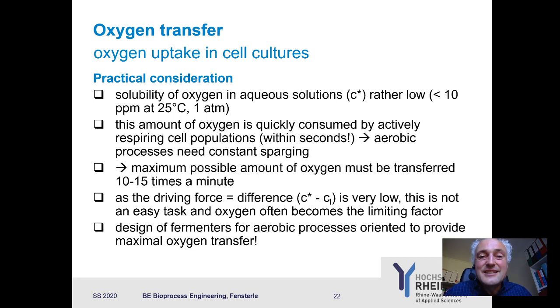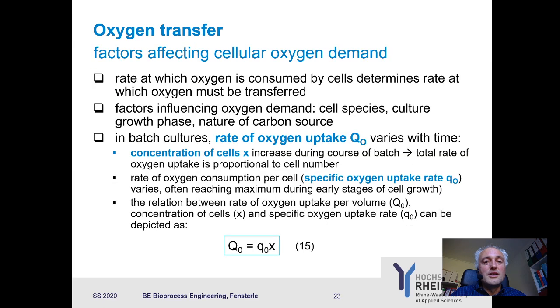But indeed, the design of the bioreactor is driven by bringing the oxygen into your reactor. This is what the whole design is about. The side effect is of course that you also optimize the transfer of your substrate to the cell, but this is not the driving force of the design. There you could use way lower stirrer powers just to achieve that.